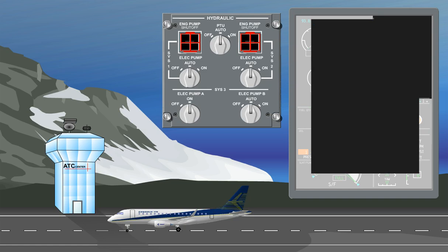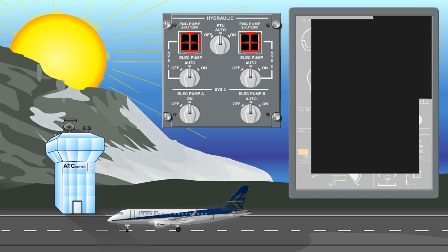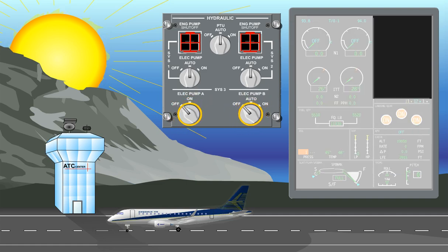During normal operation, the hydraulic system will operate at a temperature comfortably below the high temp caution threshold and considerably below the overheat warning threshold, the only exception being on-ground operation on an extremely hot day, where System 3 fluid temperature may reach the high temp threshold and cause the ICAS message to be displayed. Switching System 3 off while the aircraft is on the ground and switching it on again for flight operations can counteract this.